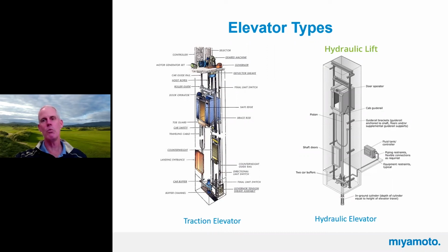If you have a wood building, we have our guide rail supports in, they have to sit there until the framer has framed all that stuff, and then they come in and put the guide rail supports in later. So it's kind of a two-stage process for the steel people, and they're coming back to the job site at different times. They would always prefer not to do that, and so would the GCs. So it might seem like it's less money to not have a steel frame in there, but it seems like it's cleaner and simpler. So that's just my opinion.